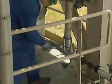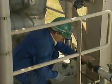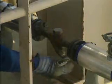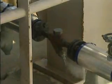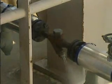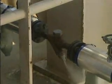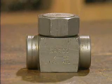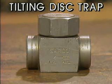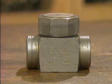In this part, we'll look at thermodynamic steam traps. A thermodynamic trap contains a component such as a disc or a piston that responds to variations in velocity and pressure that are related to changes in state of the incoming fluid. We'll look at a typical disc-type thermodynamic trap. This example is a tilting disc trap. It's designed to handle low to medium condensate flow.